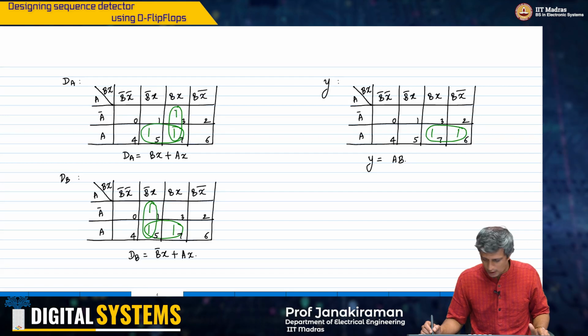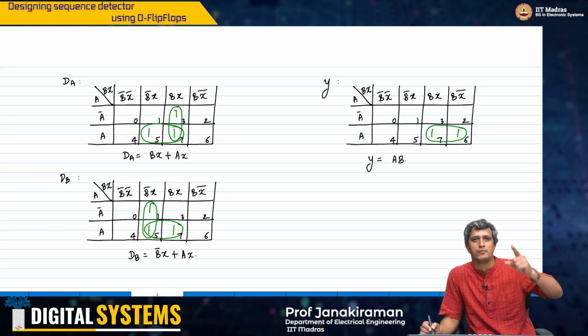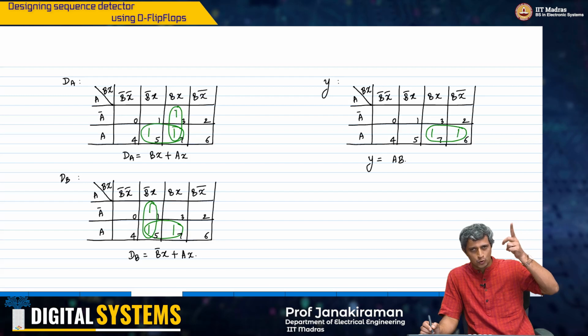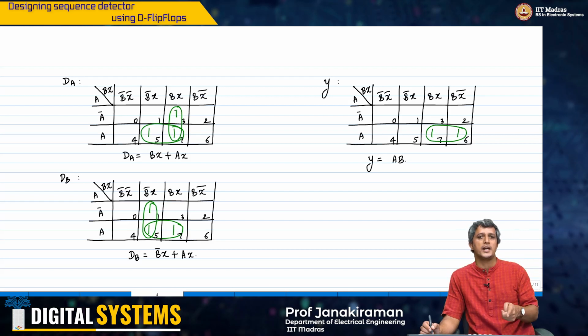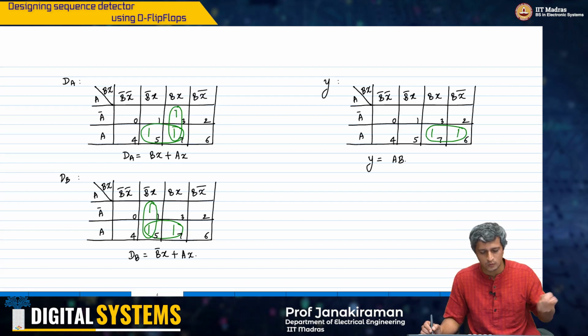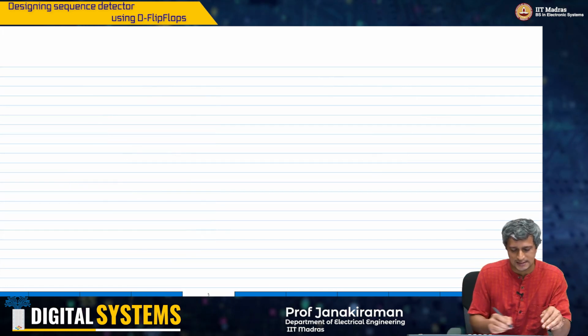So therefore we came from the state diagram to the state table to the state equations, and we can go ahead and now implement the circuit exactly.